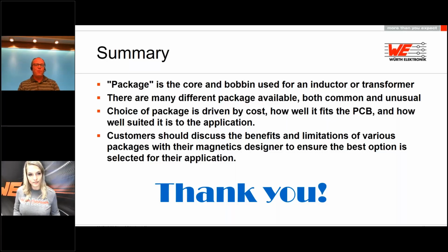So yeah, it's all relative. I guess when I say higher power, you pretty much need a larger package. So for something like an EP, they're only commonly available up to an EP13, whereas your ERs are available up to ER28, which is probably 4 times the size.